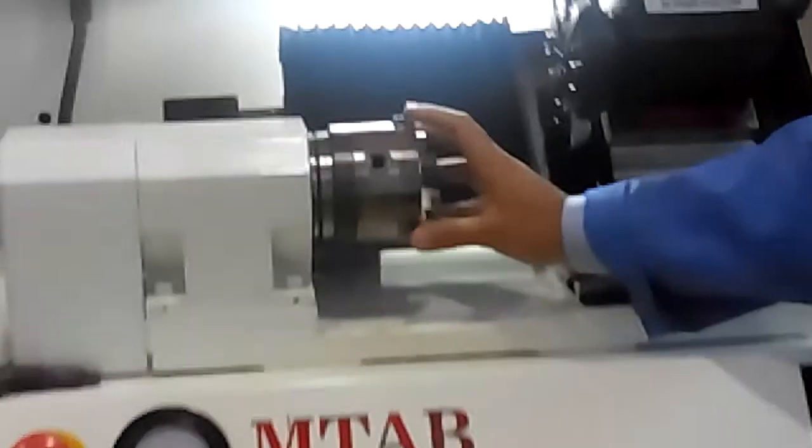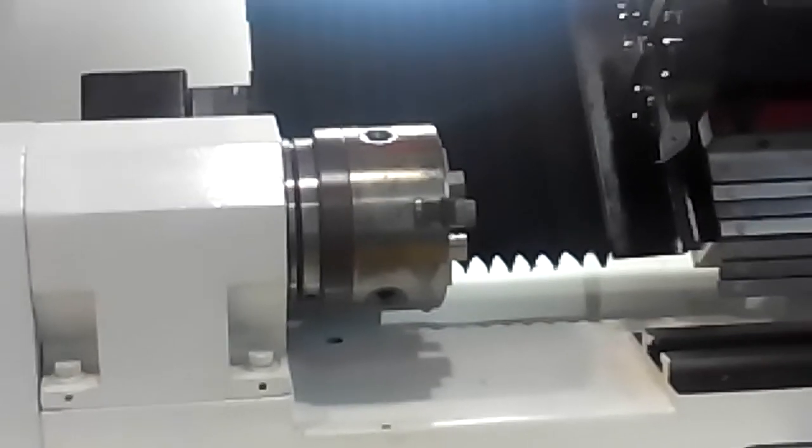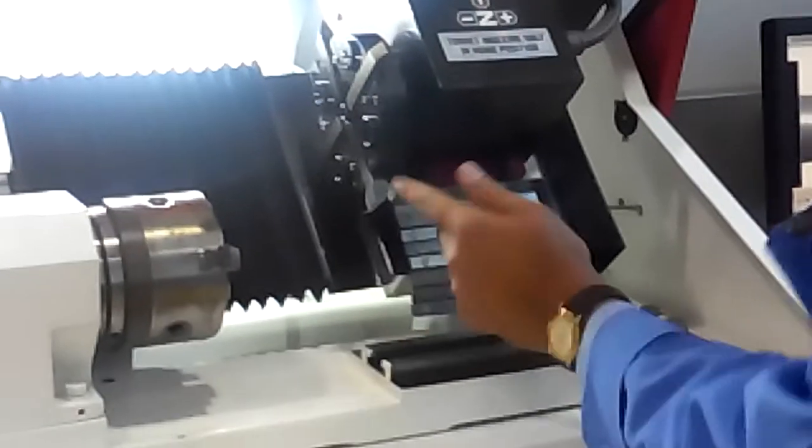Just open this one, and this is the headstock. Make sure that nothing is clamped here other than our workpiece, and the tool is there in a safe condition, whatever tools we require. And make sure that your tool number matches with your program here. See, here the left hand tool is on 5 in this machine, but another machine may have it in a different position. So in the program you have to specify that particular tool number, so that it will choose the same tool to cut.